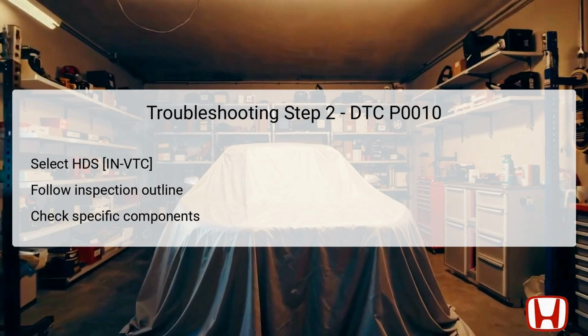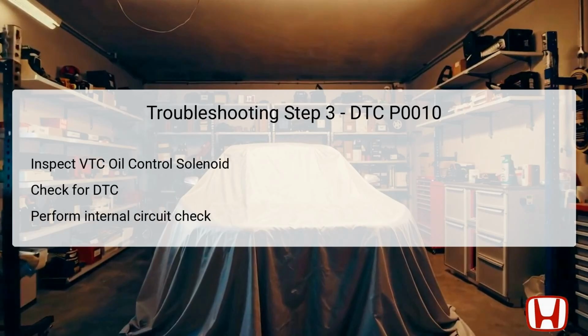The component inspections focus on the VTC oil control solenoid and related circuits, which are integral to understanding whether they are functioning correctly. The third step in troubleshooting involves inspecting the VTC oil control solenoid valve A directly. Disconnect the solenoid valve connector before testing to prevent electrical short circuits during the diagnostics.